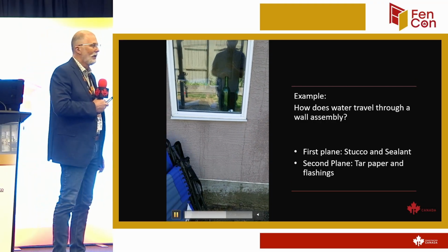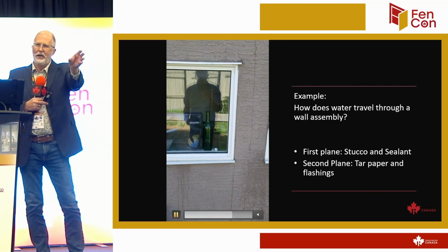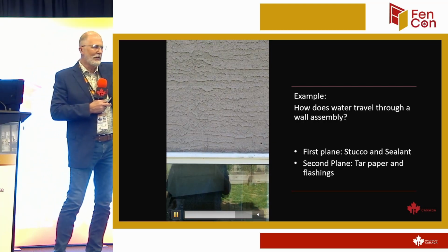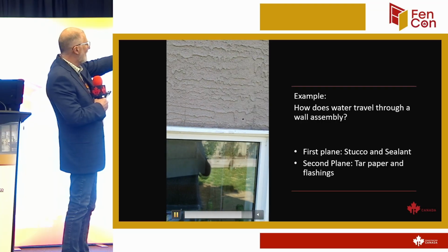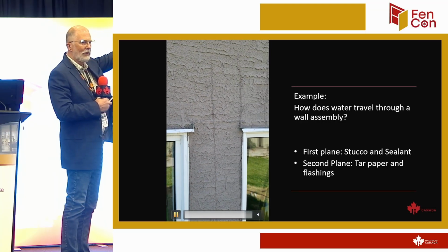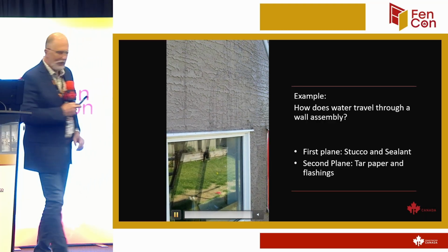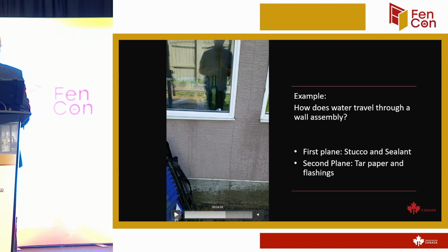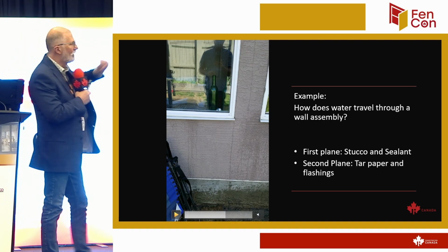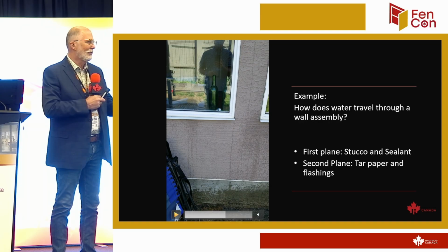Partly capillary. But if the water gets in behind the window and it runs down, doesn't it also run a little bit sideways? Now, look at the head of the window. How does the water get out of that flashing? That flashing is supposed to take second plane of protection water and dump it outside, but you just sealed it. Now, the other thing about this, if you look at the video closely, I'm just going to back it up for a second. Look at this location right here. What do you notice happening underneath that window? It's draining, it's wet. Right?